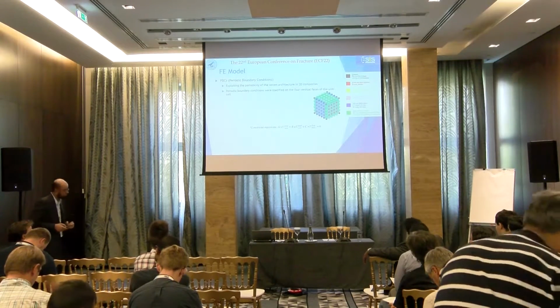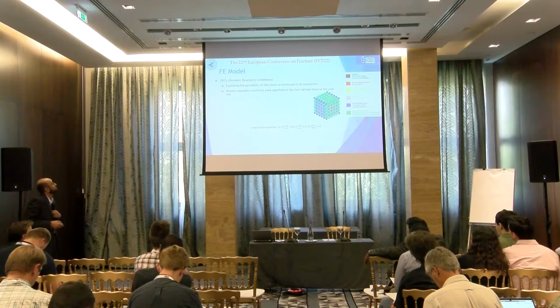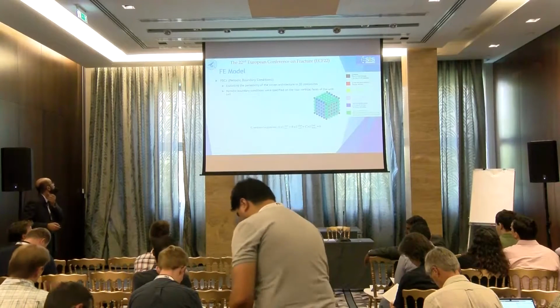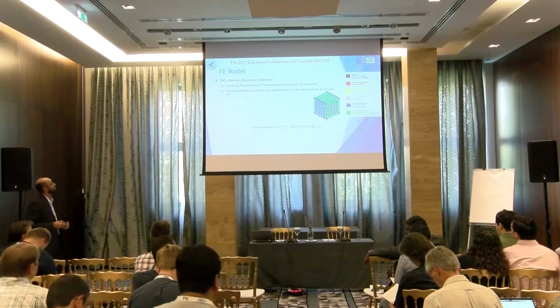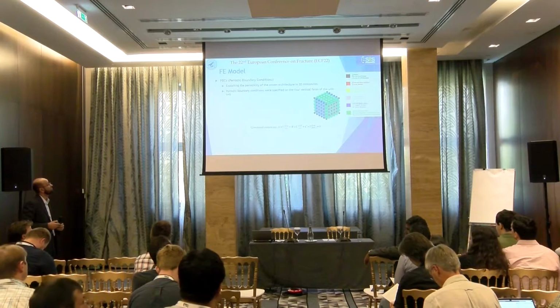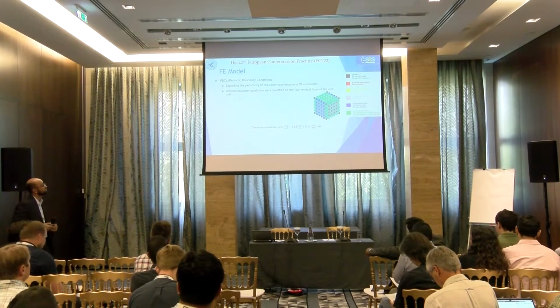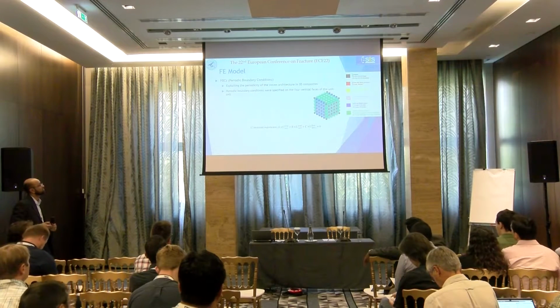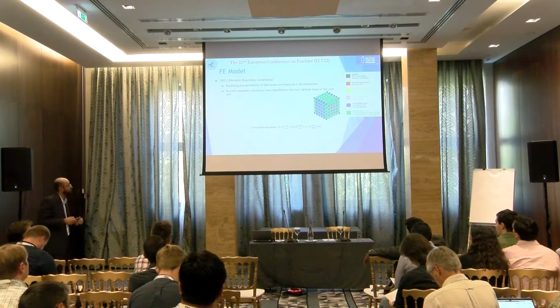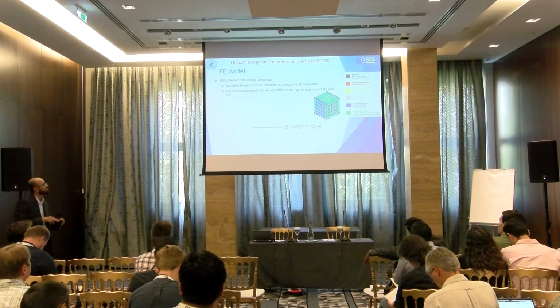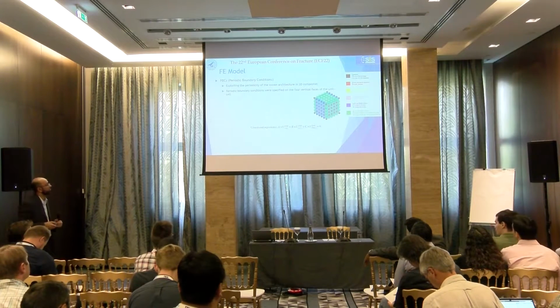Now I will come to the periodic boundary conditions. Exploiting the periodicity of the woven 3D architecture, the periodic boundary conditions were specified on 4 vertical faces of the unit cell, which is this one. We have left the top and the bottom faces because the complete thickness in a unit cell has been incorporated.